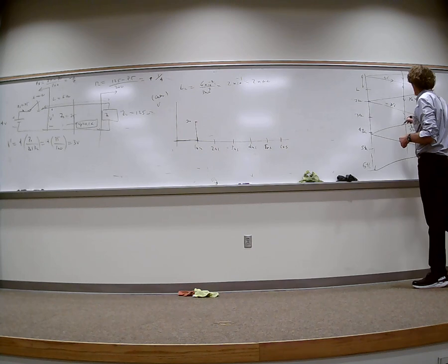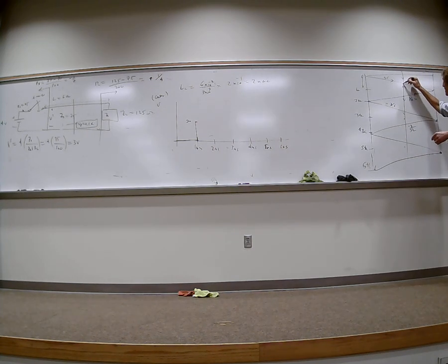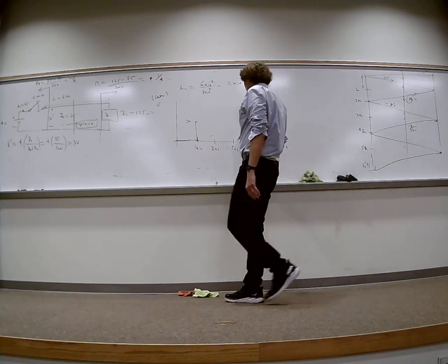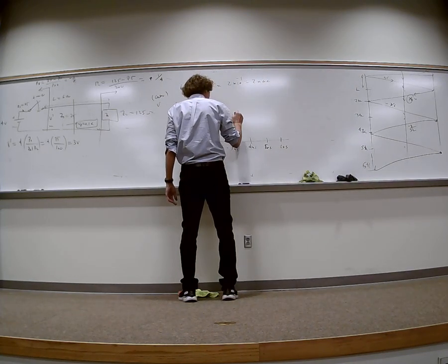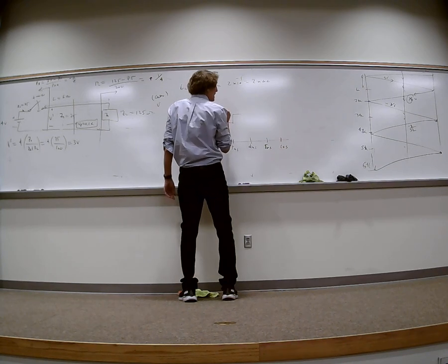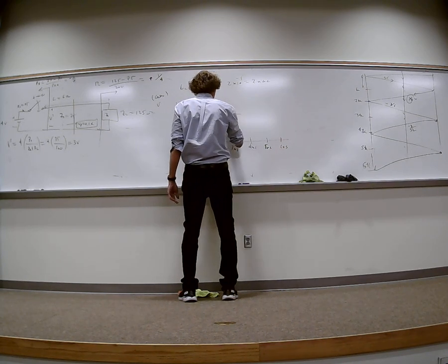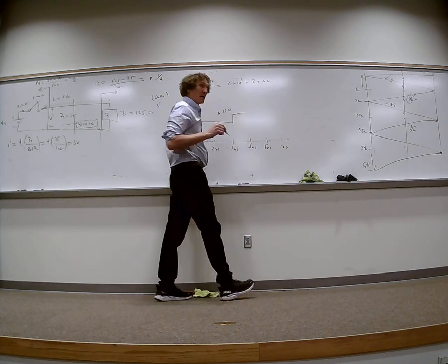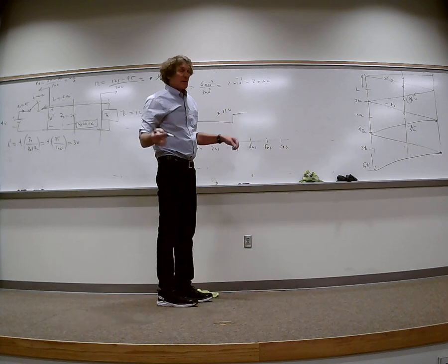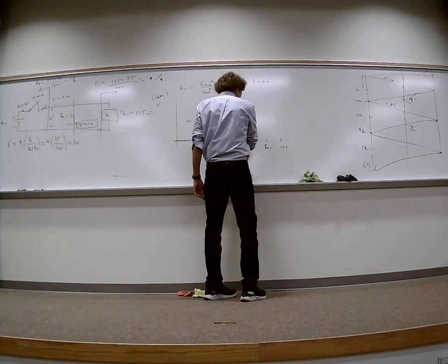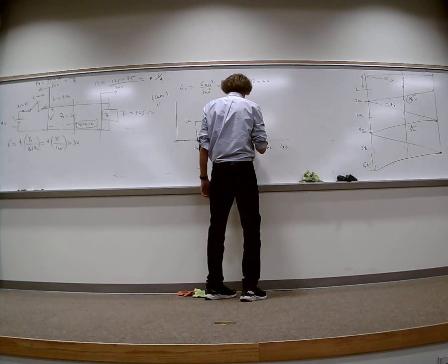So at 3 nanoseconds, it came here, hit. So at 3 nanoseconds here, I have to add 3/4 of a volt. So it's going to jump up. Does he have this graph, by the way? Does he have this as 3.75? Yep. He does. It's going to stay there for how long? 2 nanoseconds. It's going to keep going. That's exactly right. So here, that's 4.